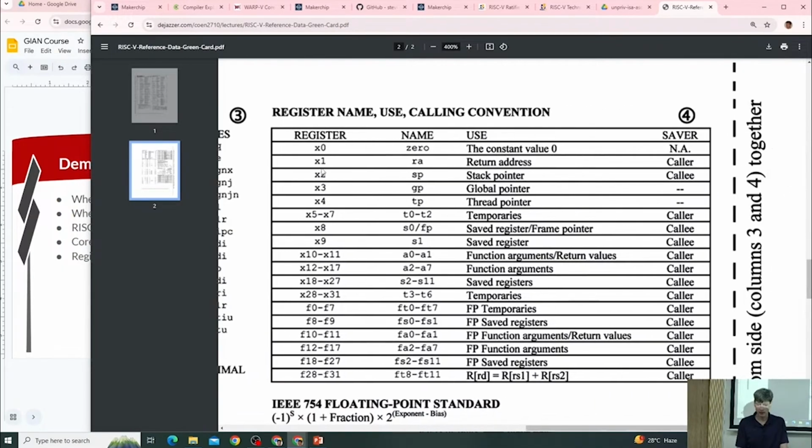So here we have kind of the register conventions, right? So I showed you the CPU is going to have a register file that contains 32 register values. Also listed here are these F registers. So the X registers are the integer registers. If you have the floating point extension, you also have these F registers, also 32 of them. So just looking at the integer registers, the X registers, all the X registers can be referred to as X number. They also have a name that reflects their conventional use.